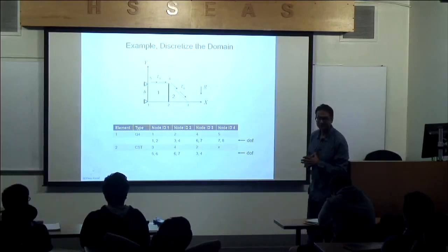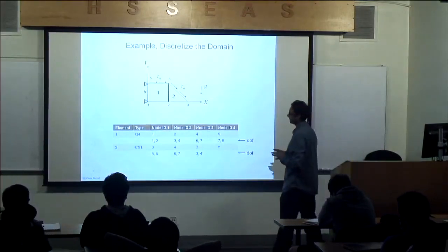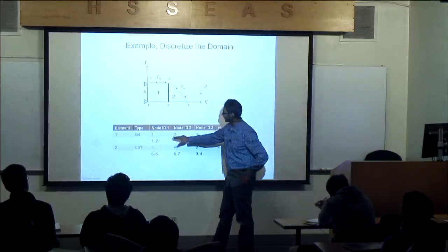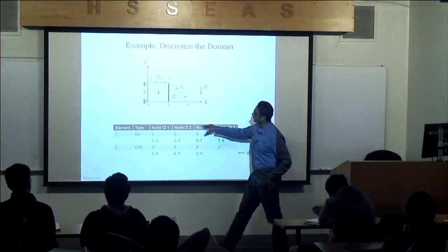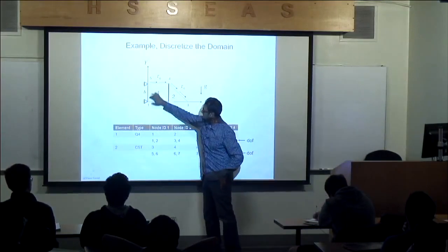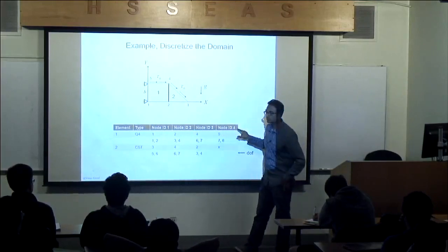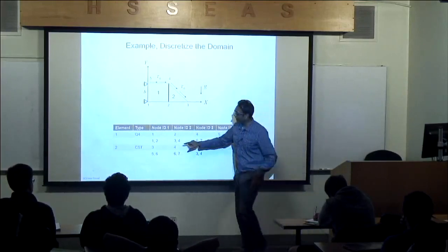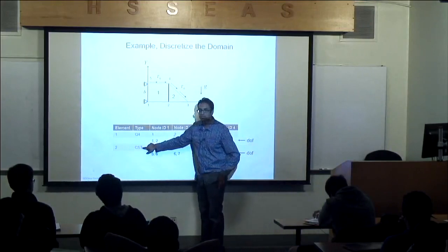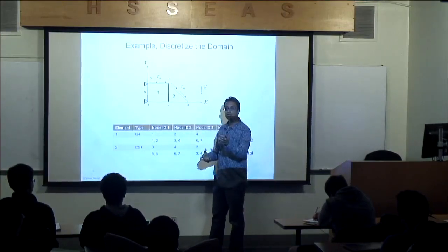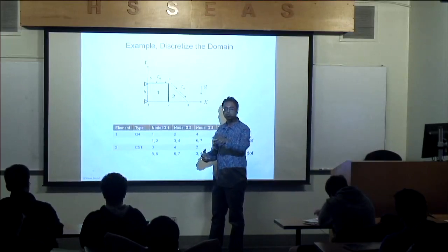Let's work. I can teach you the concept. So for element 1, I'm going to use a Q4, and I'm going to use nodes 1, 2, 4, 5. That will be the way I'm going to number them. The IDs are 1, 2, 3, and 4. For the second element, I'm going to use a constant strain triangle, also known as Tria 3, or in Abaqus, CPS3 or CPE3.